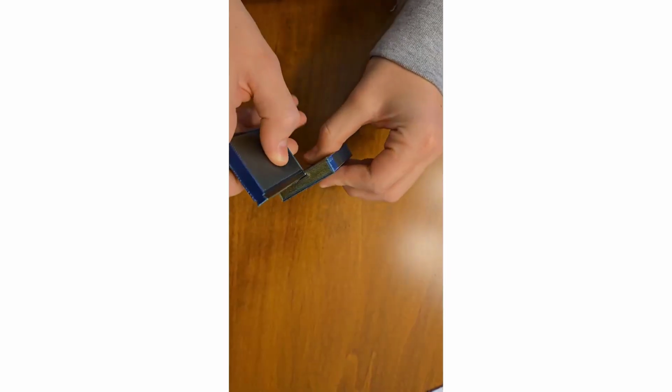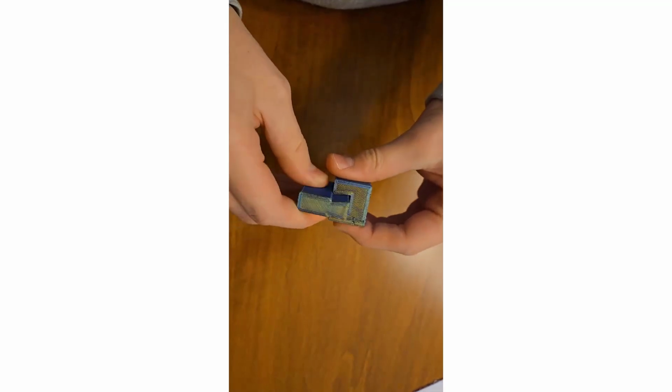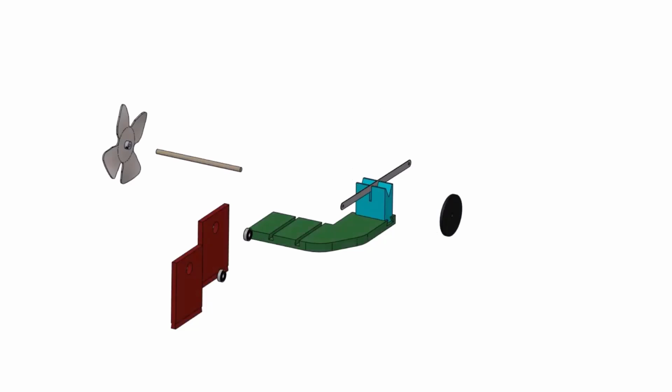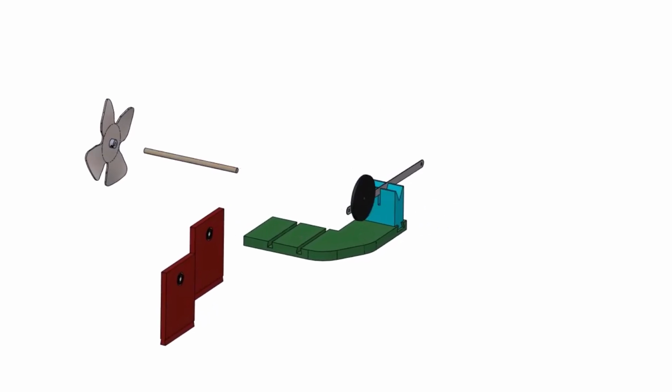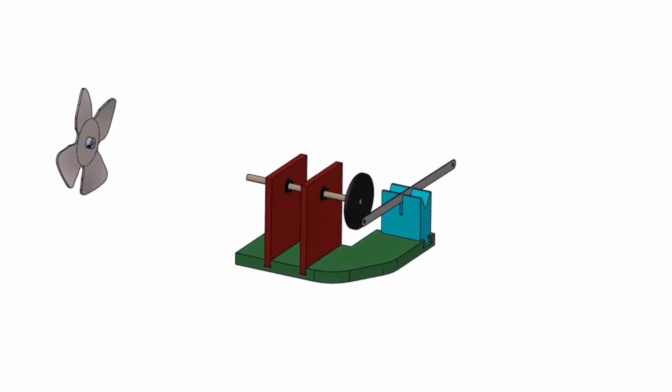Experiment with different interfaces and clearances. Print small sample files first until you are comfortable with the interface dimensions. Take care to design each component to integrate with the purchased parts. Putting all your parts together in CAD will allow you to simulate how it all works together, and will draw attention to any alignment issues before any final parts are printed.